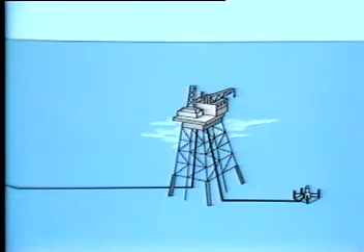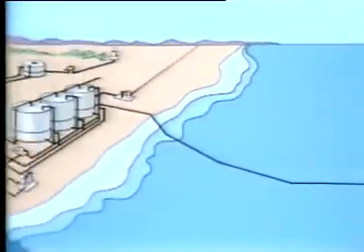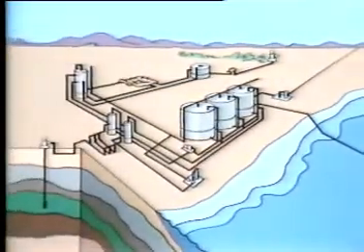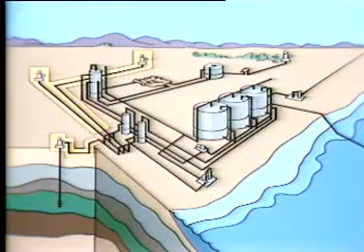The produced fluids leave the Christmas tree and enter a surface flowline system, usually a 2 or 3 inch pipe, which may be on the seafloor for subsea completions or below or above ground at onshore installations. If the production facilities are shared by a group of wells, as is often the case, the flowline will probably connect to a header or production manifold.